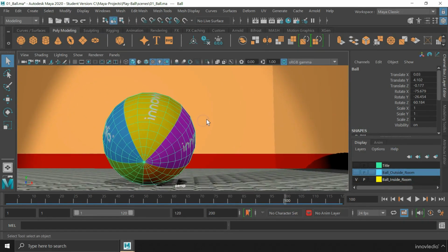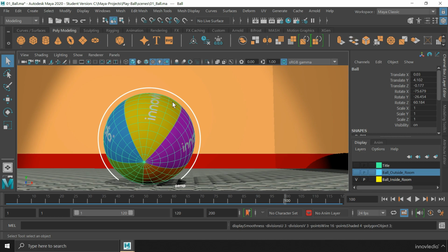You can see that the surface of this object has become a little jaggy due to the little polygons being flat and not curved as before. While if you press number 3, it will activate the smooth display mode for objects, where the surface will appear smooth and rounded. And if you press number 2, it will activate the intermediate mode between the rough and